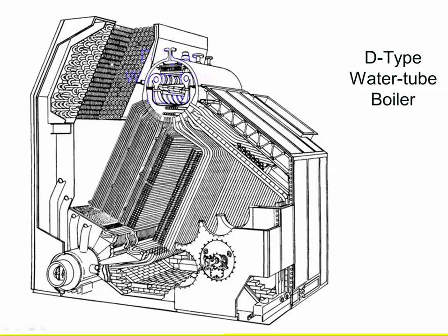So the main thing to think about is that the superheater tubes, by definition, have to be totally empty of liquid. They can never have liquid in them. If you did get liquid in them, then the boiler chemicals would scale out, cause an overheated tube, and it would rupture.